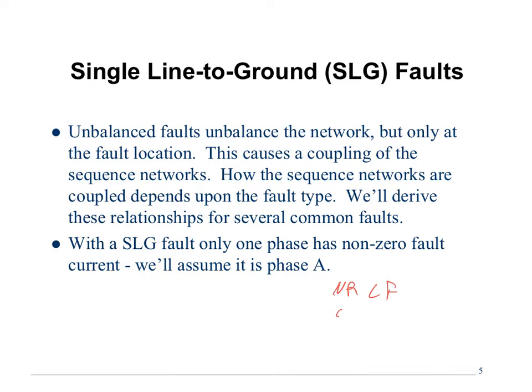It's basically V equals Y inverse times I. So if you know what some nominal loads are of the system and you have Y-bus, you can pretty quickly calculate just by using this equation to solve for your voltages, right? I can't remember what that's called in Aspen, but that's an actual diagram that you can select.